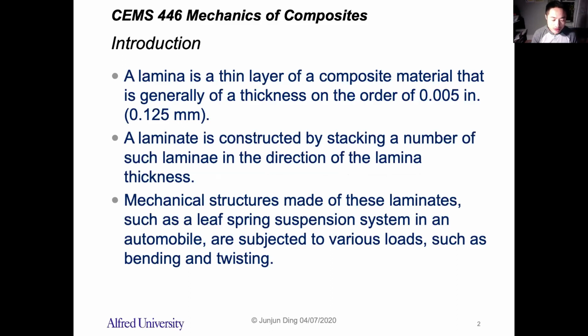Actually, for this really common composite, there's one type of composite that is called laminated fibrous composites that is made by bonding together two or more lamina so that you can get the desired properties of the laminate. And this is different from sheet laminates made by bonding flat sheets of materials, because in this laminate, you use a lamina which has anisotropic physical properties, because of the unidirectional fibrous reinforcement.